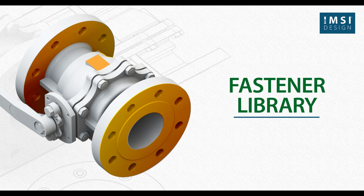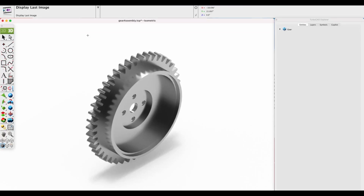Fastener library. The symbol library was updated to support a fastener library. To access the fastener library, look at the TurboCAD Explorer tool palette, select symbols, and then go down to fasteners, and you'll see there's nuts, bolts, and washers. Let's go ahead and demonstrate how you would add a bolt to a drawing.